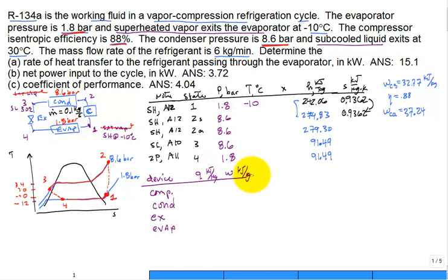And because we want to sum this column, I'd like to stay with the traditional sign convention. So around this compressor, it's adiabatic, so the compressor has 0 heat transfer per unit mass going through it. But then the work is going to be negative because it's actually work in, not out. And we find that it's enthalpy 1 minus enthalpy 2, and it comes in at negative 37.24.